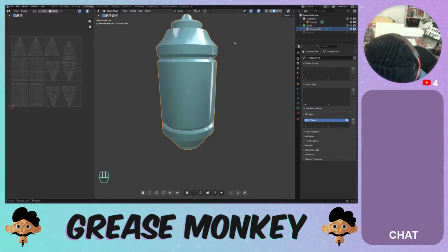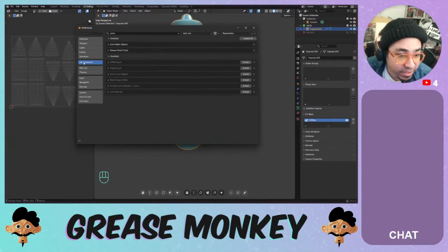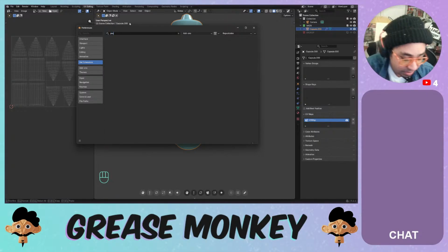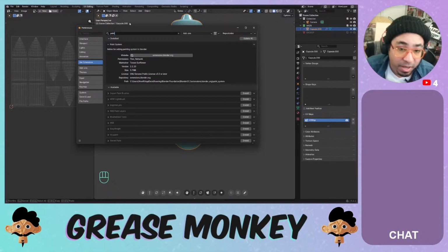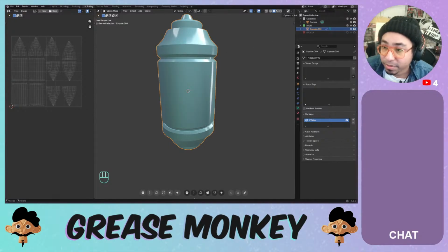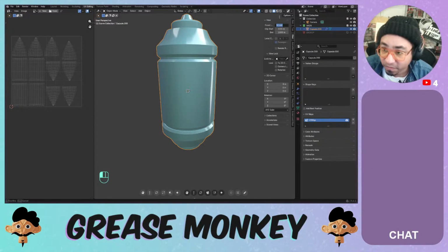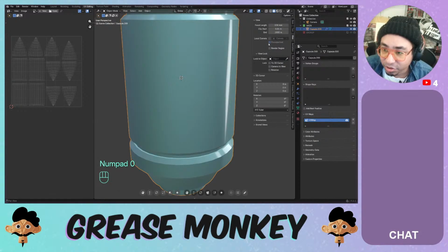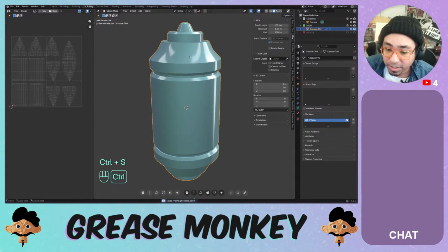The Paint System is the add-on we were trying. For anybody joining in, I just went to edit preferences. In the extensions, there is an add-on or extension called Paint System, and that's what I'm trying to learn or use to actually paint with in the viewport. We're gonna set the focal length in the viewport to like 100, so I can see less distortion. We're gonna hit save.